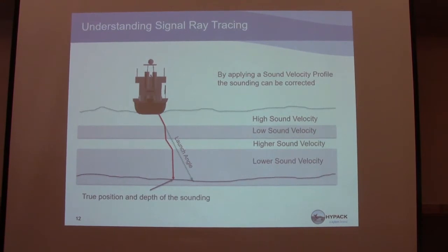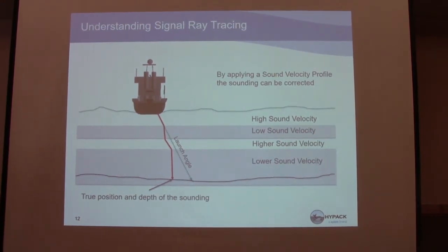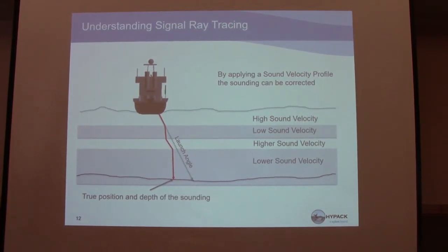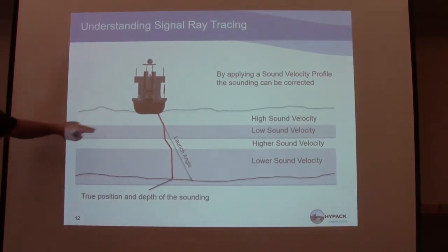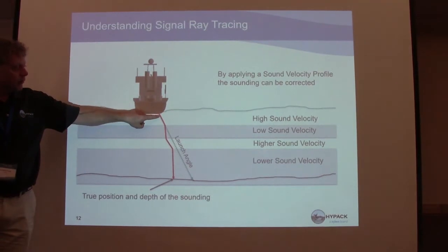Okay. HYPACK does in-the-editor ray tracing. So we collect a sound velocity profile through the water column, and we'd like to do it in many different spots around your survey area, at different times during your survey, depending on if you have tide. What we do is we map out the sound velocity through the water column and we ray trace.